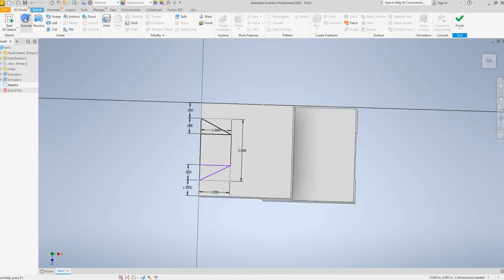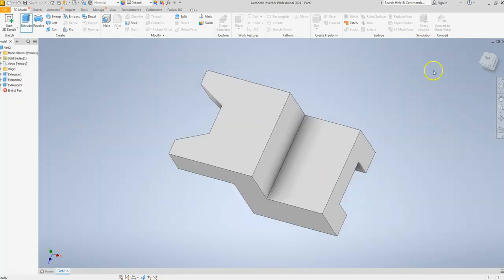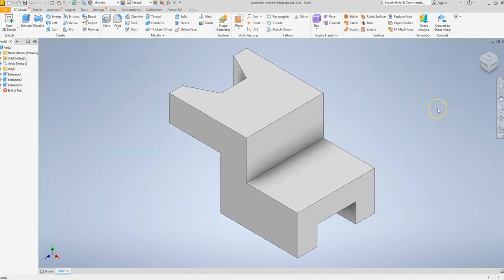So hopefully this works. So we're going to go to extrude. And then we need to click and choose what we need to extrude. So if all of your parts are completely closed off, they should turn this sage green color. You're just going to choose those 3 sections. We want to flip it. So flip it backwards, hit OK, and then hopefully you created your object that looks like this. Once you are done, you then need to put it in multi-view. So to do that, oh, before we do that, let's take one step back. Let's save our part.